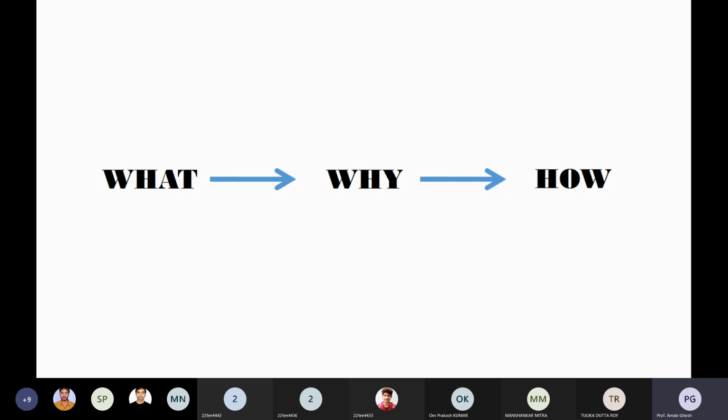That's why other subjects are also there, and there are different switching methodologies. Discussing a very common thing about switch mode power converters, another is zero voltage and zero current switching. So what happens in those cases? Zero voltage and zero current switching means you are fixing the logic in such a manner that you turn on your switch when the voltage is zero. When your voltage is zero, the current has some value.